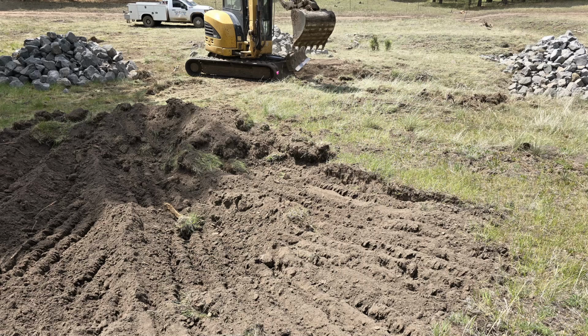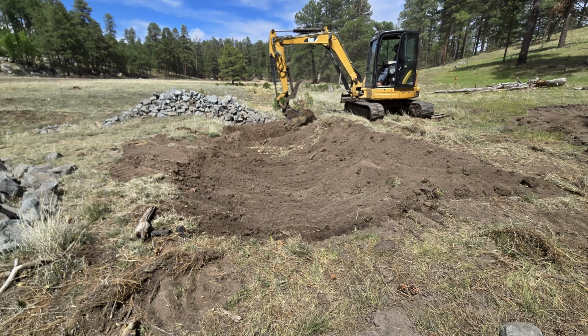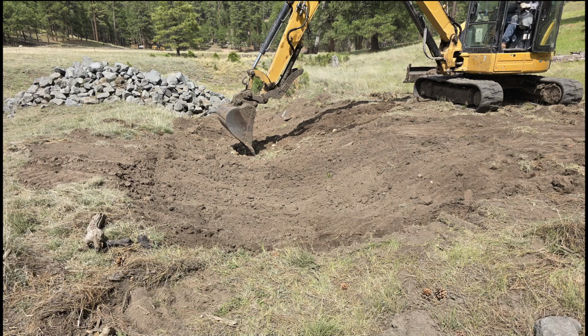Don slopes the vertical banks with the excavator. He uses the soil that is removed to fill in the washed out holes in the drainage. Some of the soil that is removed is placed in piles. This soil will later be used to form the stream banks along the edge of the rock that we place. Don shapes a wide floodplain with gradual slopes where the head cuts were located. The valley is dug deeper than the planned final elevation.